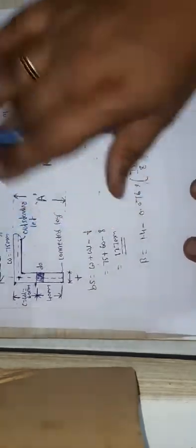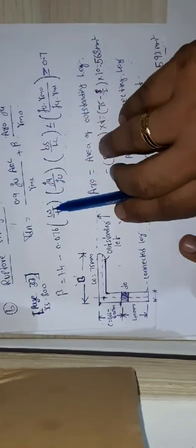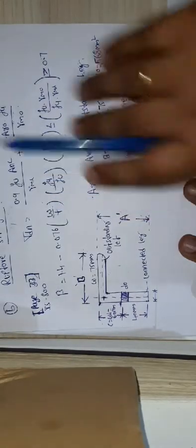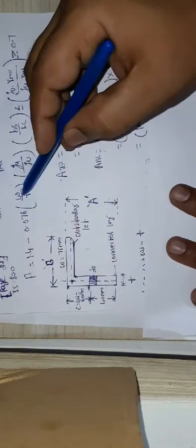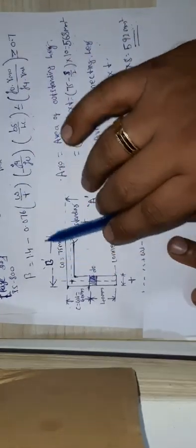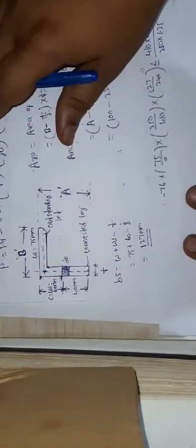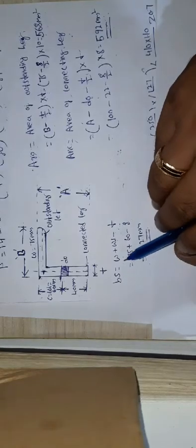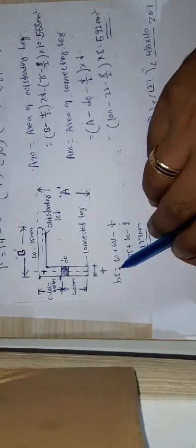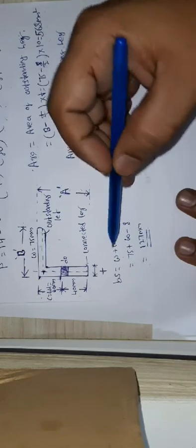Then, while calculating beta, we have several terminologies here. What are w, t, bs and Lc? w means the length of the outstanding leg. And bs means the bolt shear lag width, which is given in the code book. On page number 33 they clearly explain what this means.